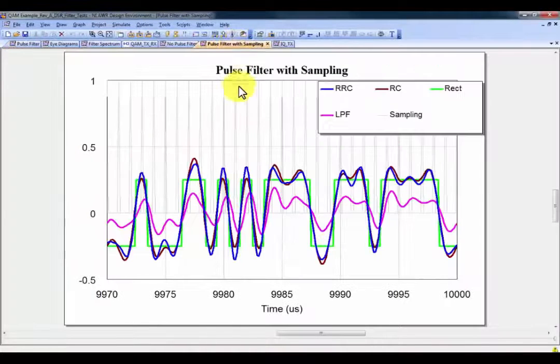And so what I've done is I've plotted the same thing we had before with a sequence of sample pulses, and you can see that these samplings are happening at the peaks. So the basic idea is I would say, okay, this is a 1, this is a 0, a 0, a 0, this is a 1, this is a 1. It doesn't have to be at the top, but you can see it's pretty high there, it's pretty high there, so that'd be a 1 and a 1, and we get a 0, and so forth.